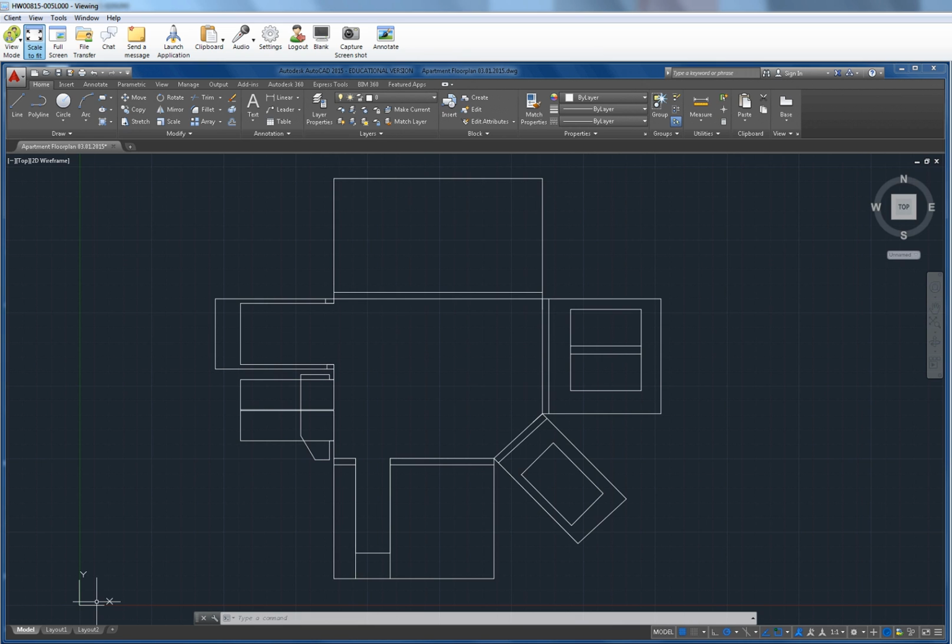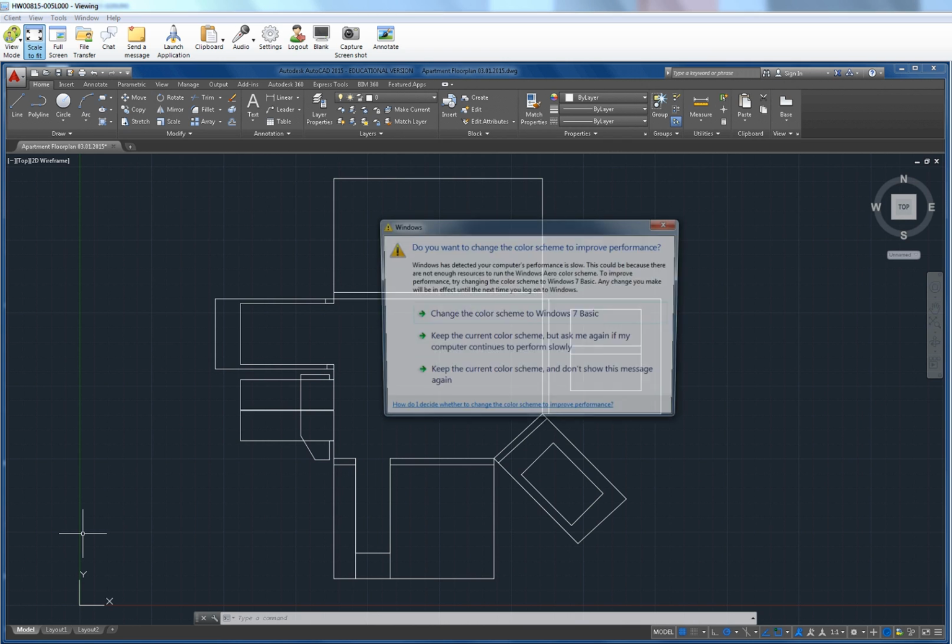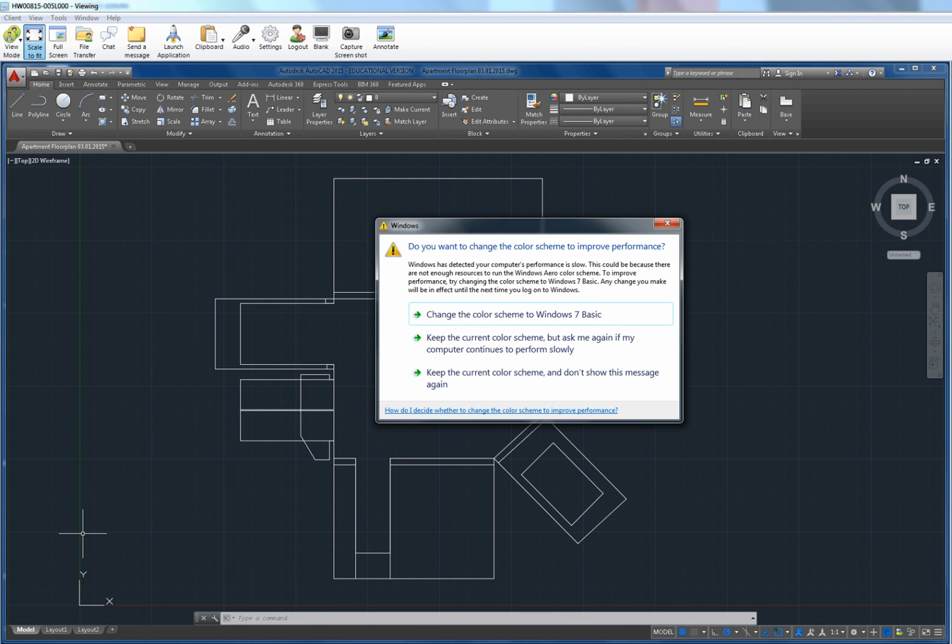you can work on the XY axis as our work surface. So I need to get this aligned with that elevation, right? So I need to take here. Right. This is X. If we look at it like this, X, Y, Z, right? We need to get like that. Otherwise, when we copy this elevation out, it would be 90 degrees the wrong way, counterclockwise.